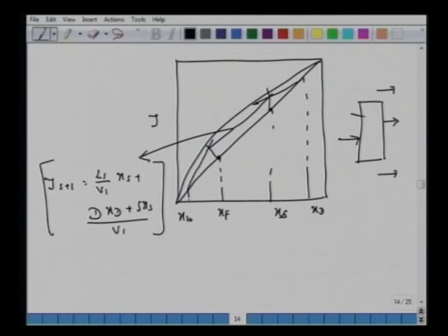One has to write down one material balance for this, one for this, one for this, so that at any trace we have two incoming streams, and the two leaving streams are in equilibrium, whether you are in this region or in this region. Of course the flow rate here was L V, here we have L bar V bar, and here we have L1 V1. So we had one feed line, one line for x s where we were drawing it, right?